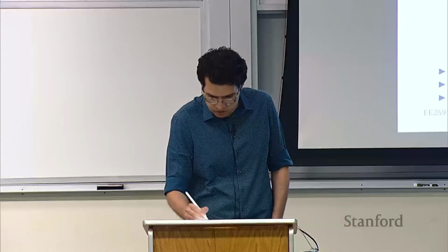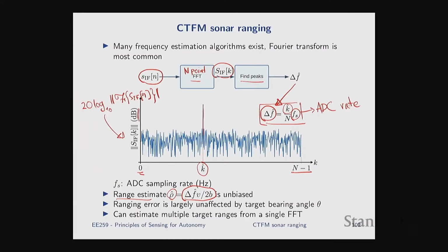Okay, make sure this makes sense to you. If it doesn't, let me know. Let's talk about it. Does this make sense, how we're converting the frequency, right? Because when you do the FFT, for your index, index 0 corresponds to 0 frequency, and index n corresponds to the sampling rate, which is fs, and every index in between is just linear, right? So every FFT bin has a width of fs over n, where n is the number of points in the FFT. So that's why you just multiply your k hat by fs over n, and that gives you the actual frequency corresponding to it.